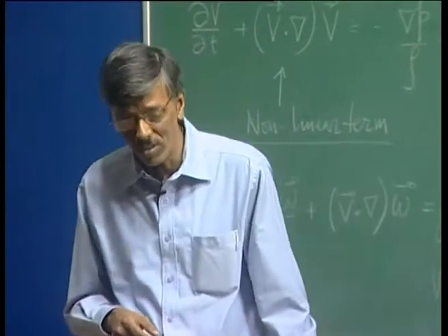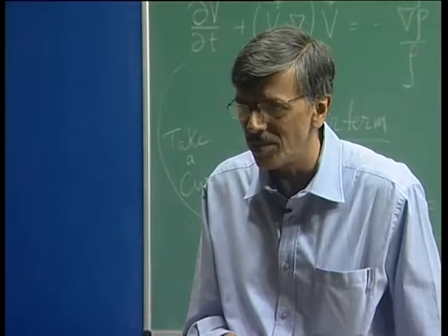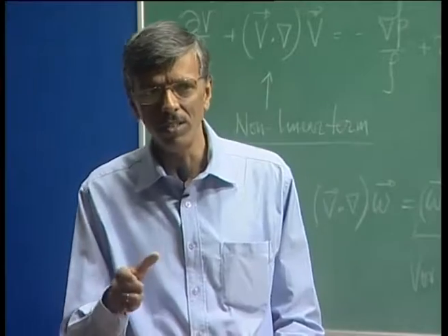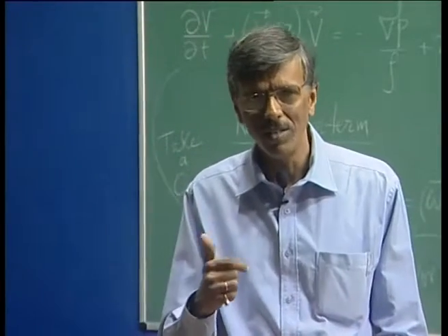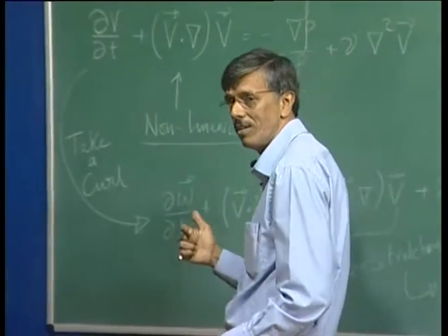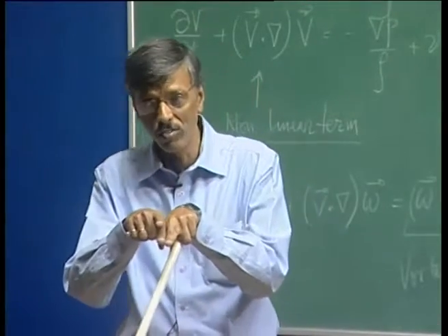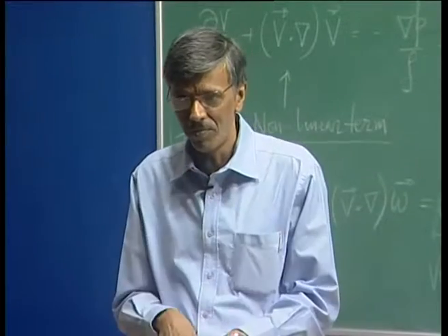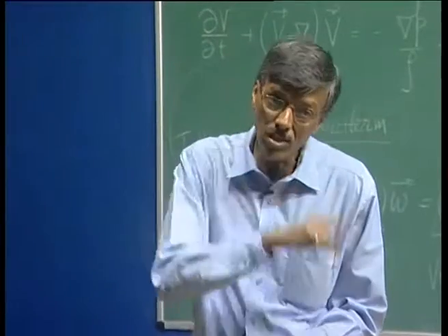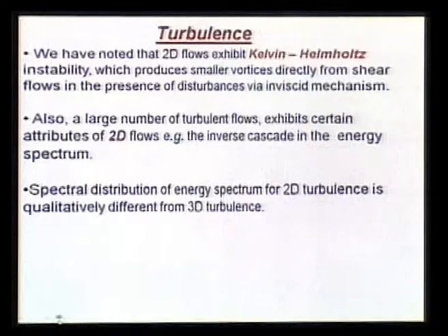And what was so important about Kelvin-Helmholtz instability is that it was an inviscid mechanism. So you do not need the presence of an elaborate viscous mechanism to show up the instability. You can directly get it from a two-dimensional flow. You have the shear. Shear is of course synonymous with viscous phenomena, right? But we are talking about the disturbance growth mechanism. That could be a completely inviscid mechanism. That's one thing we must understand.